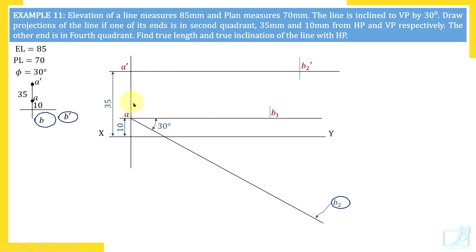Already there are horizontal vertical lines. Now through B2 dash and through B1, we should draw vertical lines. Horizontal lines are already there. When you draw those vertical lines, you know which are the other points on those lines. So through B2 dash, I have drawn a vertical line. Which other point is on this line? B2. And there is already one more line on the paper that has B2 on it. So this point is B2. So we have marked B2.